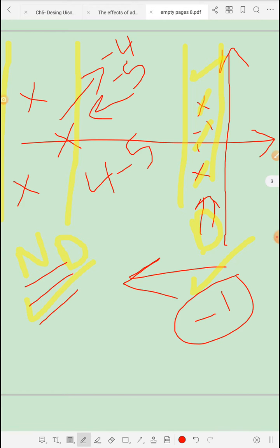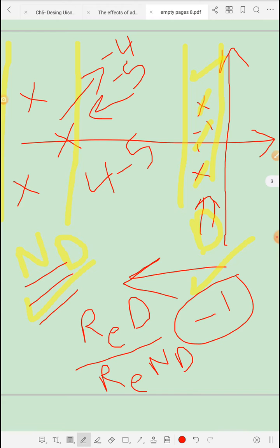If this ratio between the real part of the dominant over the real part of the non-dominant, and when we speak about the non-dominant, we select the closest to the right, and if this closest to the right is satisfied, then the others which are to the left of this one will also satisfy the condition.